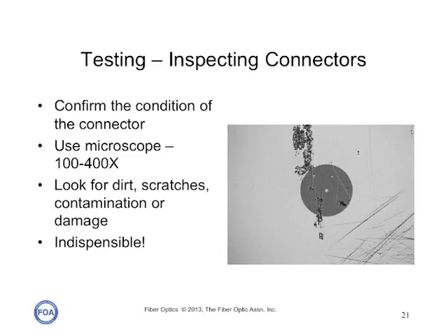Once we install our fiber optic cabling, we test it. And one of the first things we do is inspect all the connectors with a microscope. We're looking for dirt, scratches, contamination, or damage. A microscope is one indispensable tool for every fiber optic installer and every fiber optic user. And the reason we say that is because you can look at a connector and tell if it's good.